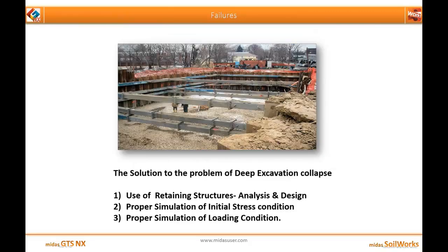Now, what is the solution to the problem? The solution to the problem of deep excavation collapses is the use of retaining structures, and their proper analysis and design. Now, for proper analysis and design, one should be able to properly simulate the initial stress condition and also the loading condition which the retaining structure is going to face during the construction period.